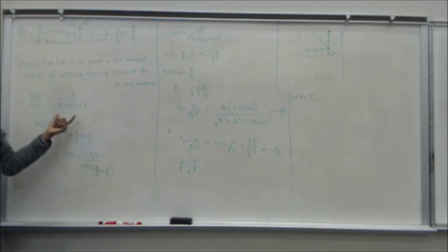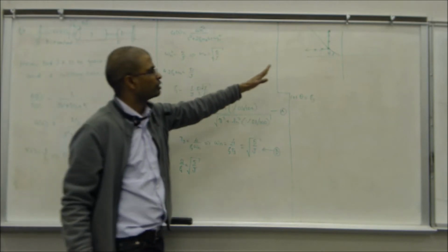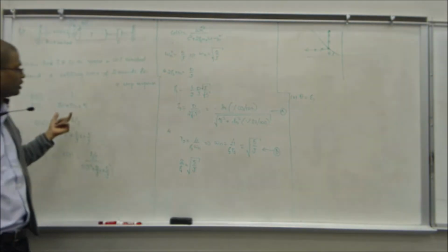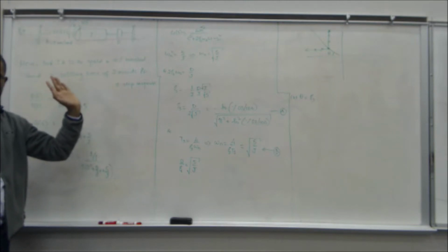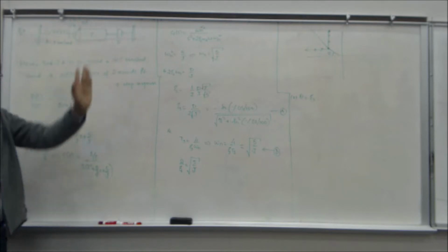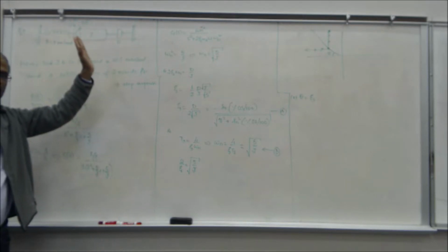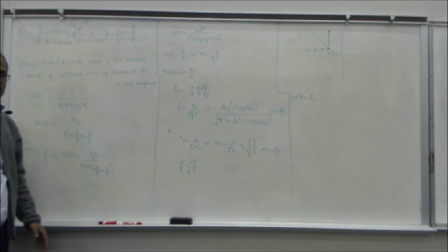So you can choose certain values of D and J to get any kind of response here, right? You can choose a value of J and D such that it increases only in the real axis, or only in the imaginary axis, or you can keep the damping ratio the same by choosing an appropriate ratio of J and D. You see it?